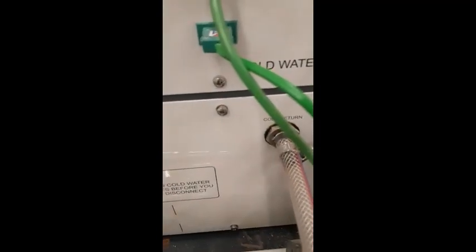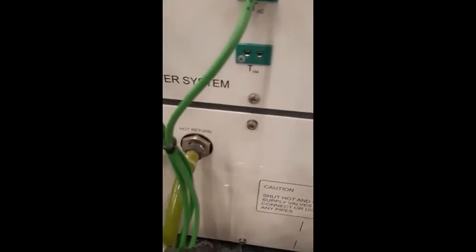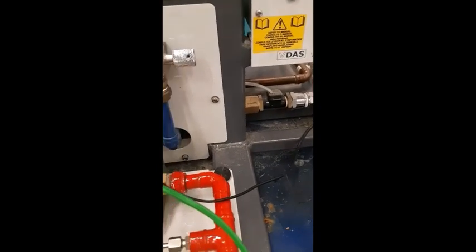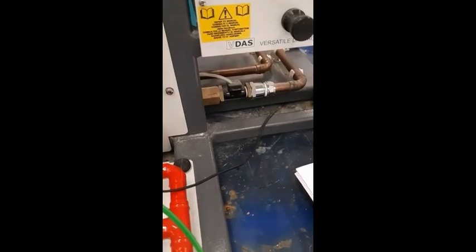So when we start the experiment today, we start with the parallel flow. If you see this sheet, this one is the parallel flow and counter flow. We do the parallel flow. What we have to do is fix the hot water flow rate at 4 liter per minute and cold flow rate at 3 liter per minute.